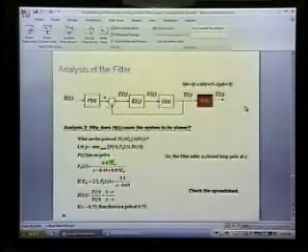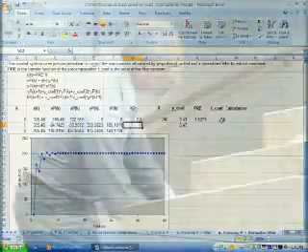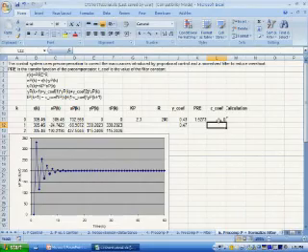P has no poles because that's a constant. We know the poles here, that's a function of the Kp. And we added this pole at C. And so when C is large and we're getting the smoothing effect, then, let me show you that. Let's change this to 0.75. As we get smoother over here, we're also taking a longer time to settle than if we had essentially no filter at all.